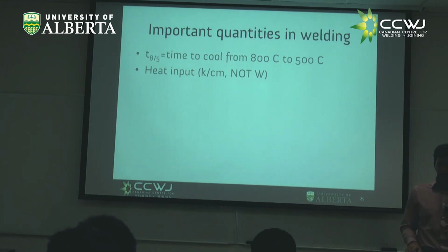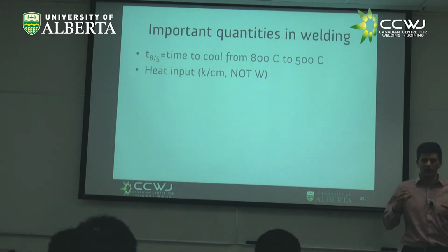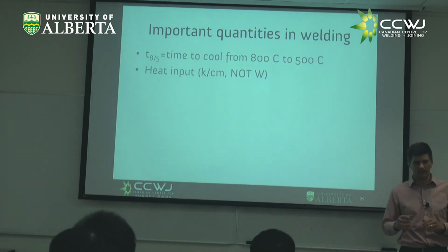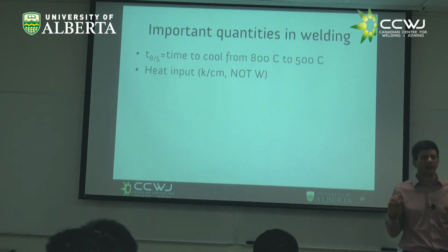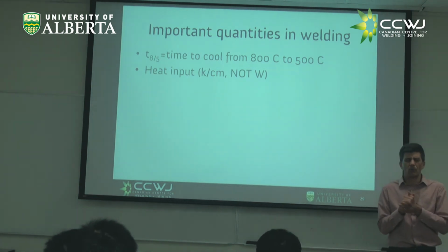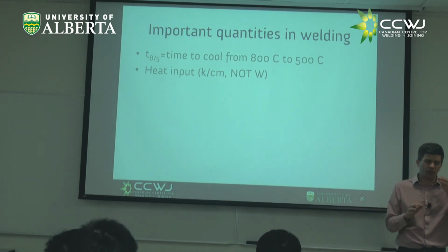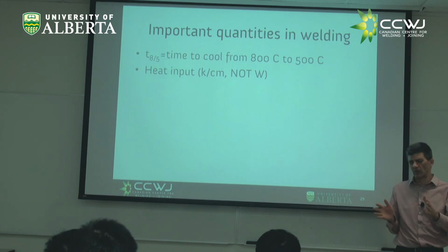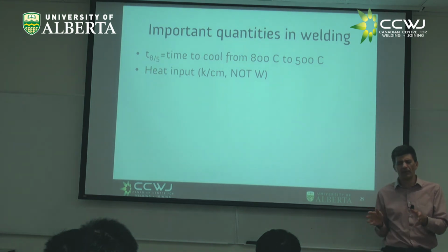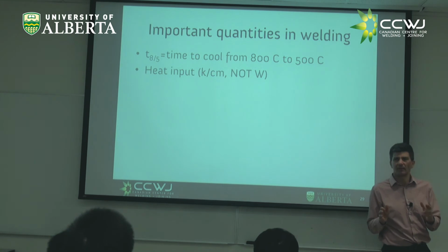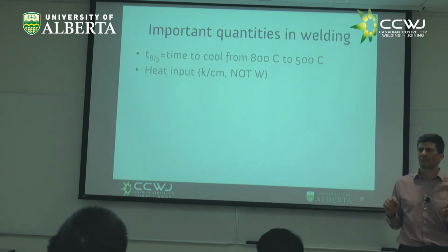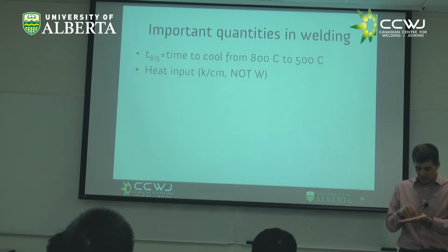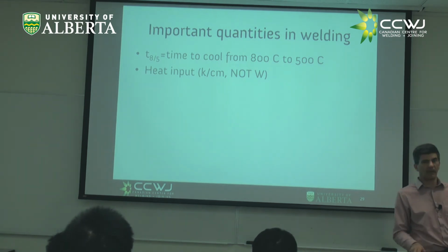The other thing is heat input. And by heat input, we talk about kilojoules per centimeter, not watts. That means how much energy I put in each length, right? For example, if I'm welding one stringer bead and another weld in similar parameters, but it's a weave bead, which is going to have higher heat input? Say? Stringer higher heat input? I think the weaving, because I'm putting lots of heat and advancing little, right?